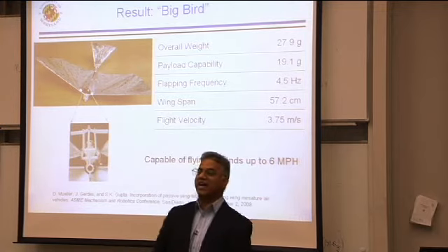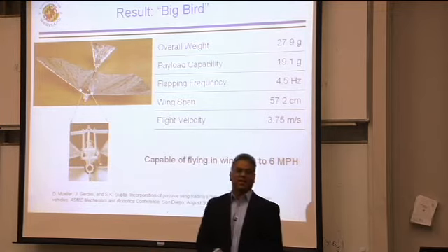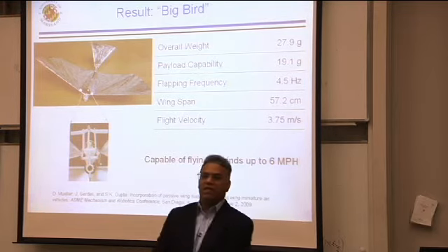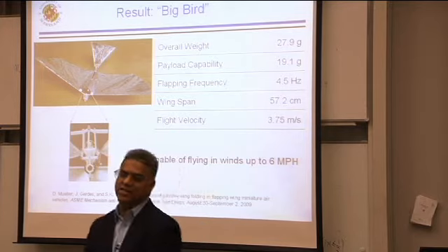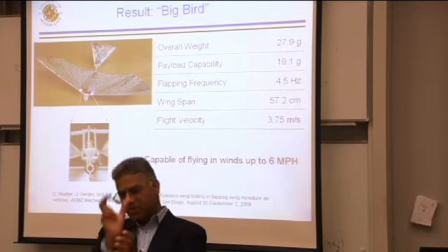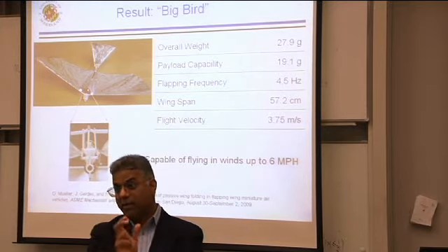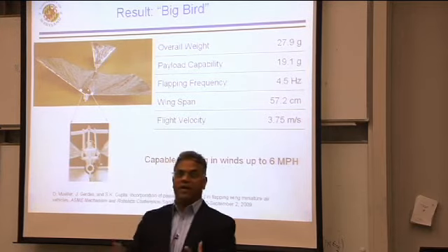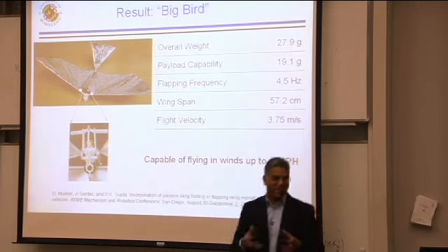So then we had to think about multi-material molding. If we do multi-material molding, we do in-mold assembly instead of creating a single monolithic advanced polymer composite structure. Then we can actually do better. But then the synthesis problem gets much harder.